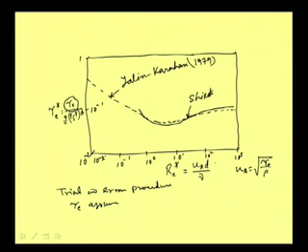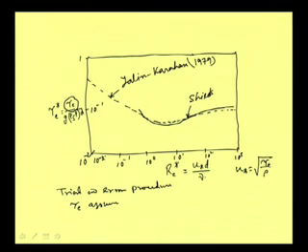Suppose for a particular size of the bed material, the effective size we can take, then we know the nu value. So, for that tau c we will be getting an Rc star value. Now, from this Rc star, from the graph we need to see what the tau c star is. Once we get the tau c star, again rho, g and d are known, so we can find out what tau c is.